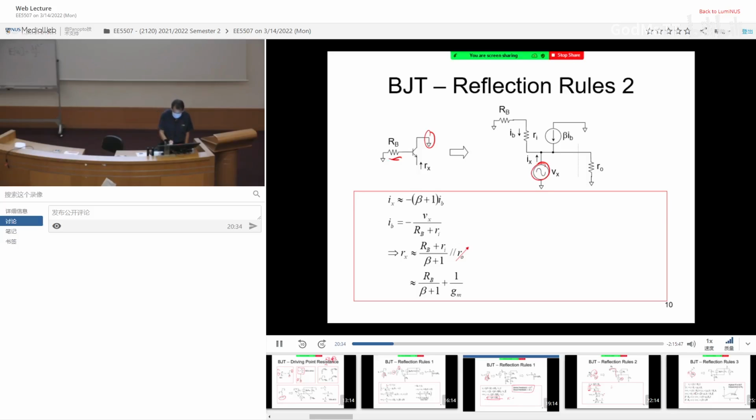If this is the voltage, you can see this R0 is directly in parallel connection with this Vx. So in fact, if I consider this whole thing as one whole network, I don't know what that is. But that resistance eventually is going to be in parallel with R0 to give you Rx. You get the point? So if you look at this circuit, it consists of 2 portions.